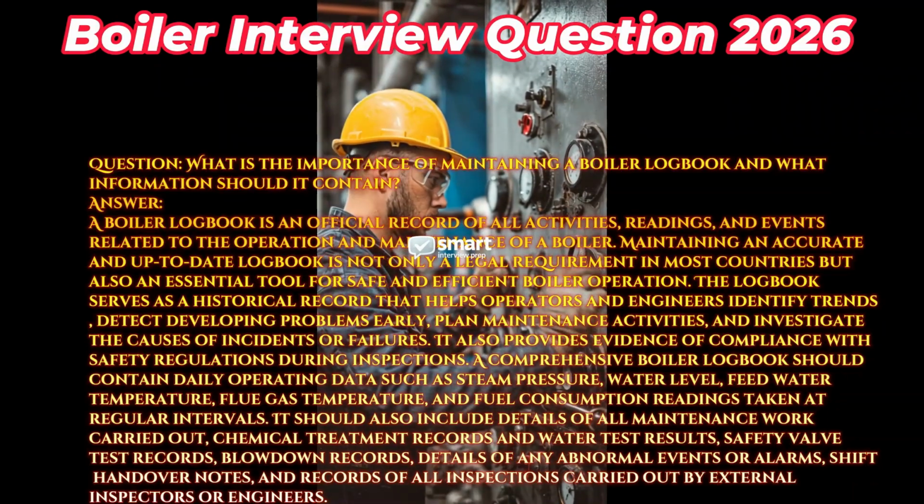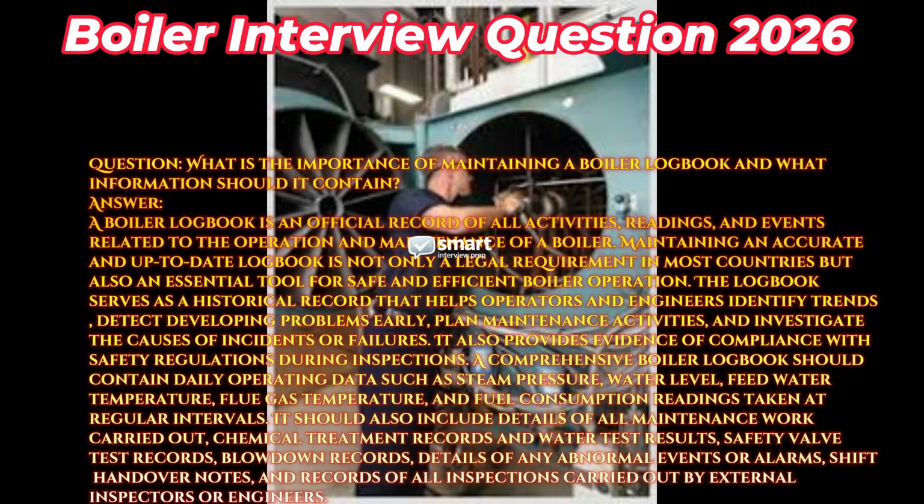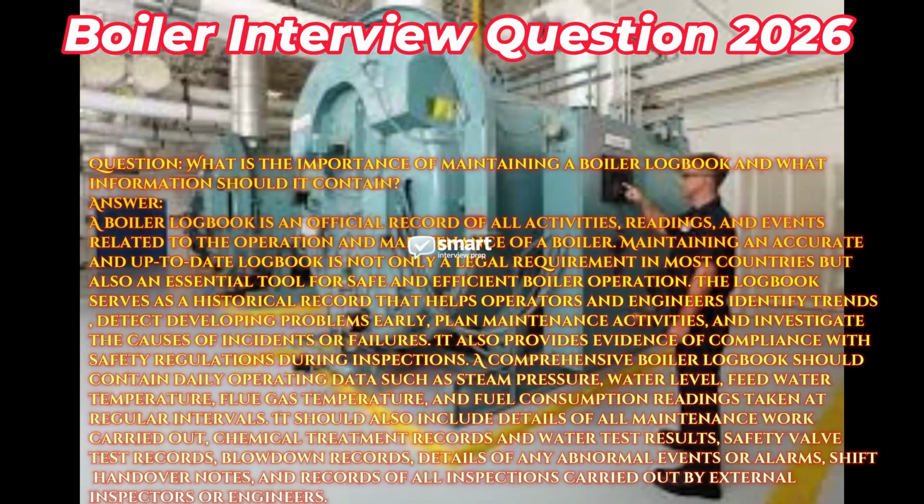It should also include details of all maintenance work carried out, chemical treatment records and water test results, safety valve test records, blowdown records, details of any abnormal events or alarms.